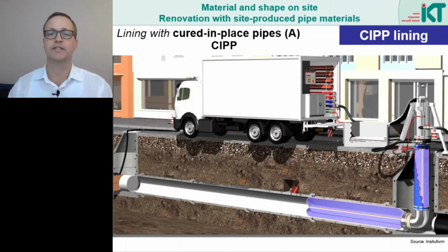On-site quality assurance naturally plays a special role in the liner process because both the pipe material and the pipe geometry are created on site. This means that the pipe is always thoroughly inspected with the camera after installation and, as a rule, pipe samples are also taken to test the material properties in the laboratory. In most cases, these samples can be taken in the manhole area without damaging the actual rehabilitation result.